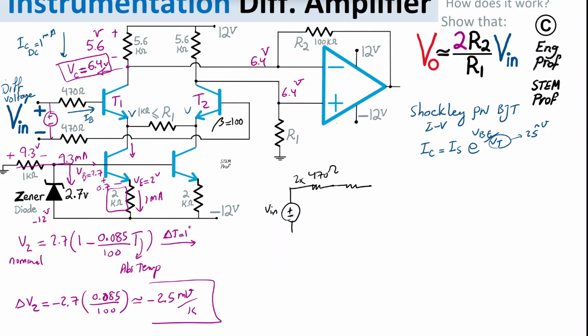So I'm going to basically say 2RB, which is another name. We can say it's 2 times the terminal voltage divided by the base current. So that's the value of this resistor, 2 times RB. Then we have R1, which we assume is more than 1 kilo ohm for practical reasons, say a resistor between 1 kilo ohm and a few hundred kilo ohm, say 200 kilo ohm. Then R1 reflected to the base from the emitter is beta plus 1 times R1, and it's just one R1, not twice, and that goes back to the negative terminal.